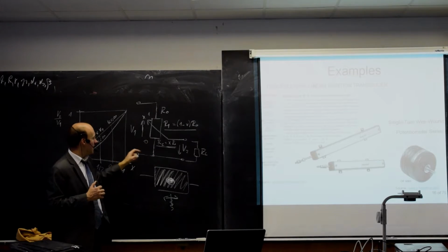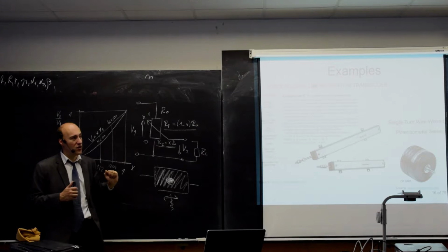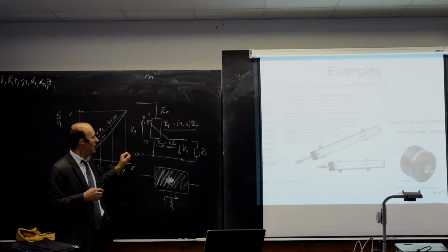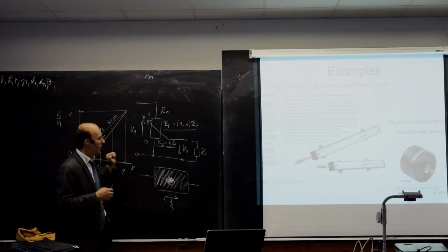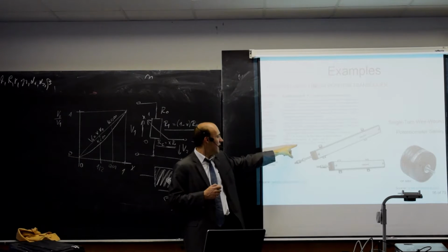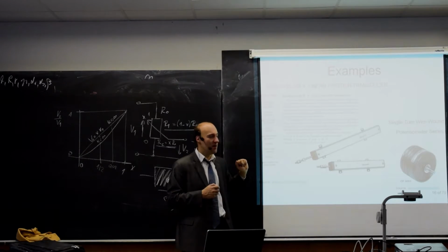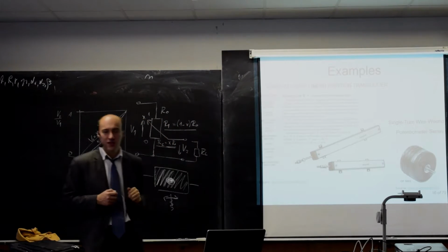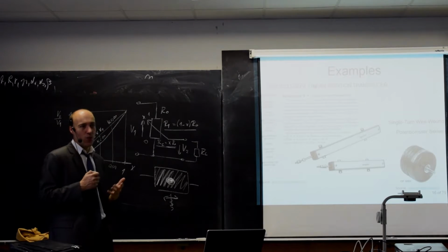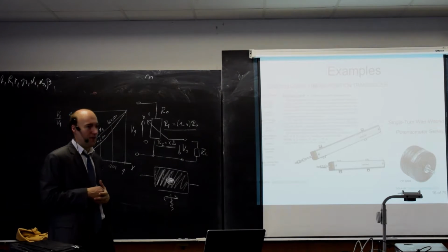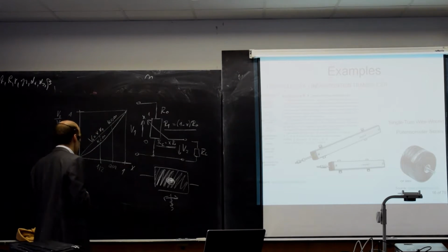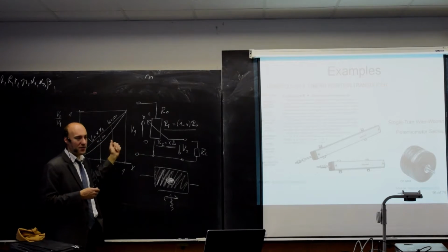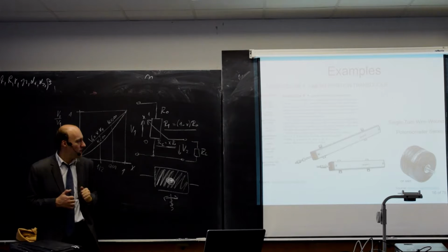So typically, this maximum current is limited to a value of roughly 100 milliamperes because we want to prevent heat in the sensor itself. So here you see the maximum allowed current through the sensor is 100 milliamperes, and therefore the maximum voltage is roughly 30 volts. That's also for security reasons. We don't typically want higher voltages than roughly 50 volts. So you cannot connect an arbitrary voltage to the sensor. You are limited by the current that can flow through it.